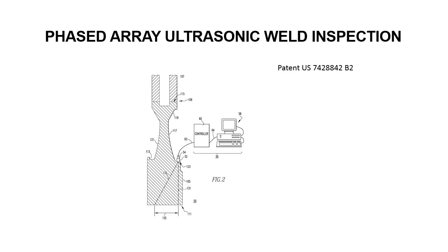All right, we're going to touch base on phased array ultrasonic weld inspection just for a minute. I'm going to pull it out of the Wikipedia page. The principle of operation for phased array: the phased array probe consists of many small ultrasonic transducers, each of which can be pulsed independently. By varying the timing, for instance by pulsing the elements one by one in a sequence along a row, a pattern of constructive interference is set up that results in a beam at a set angle. In other words, the beam can be steered electronically.